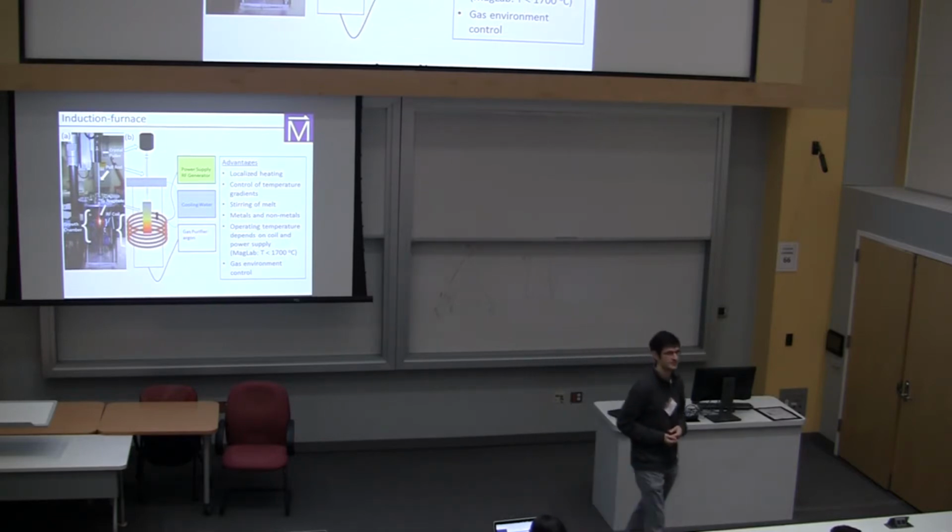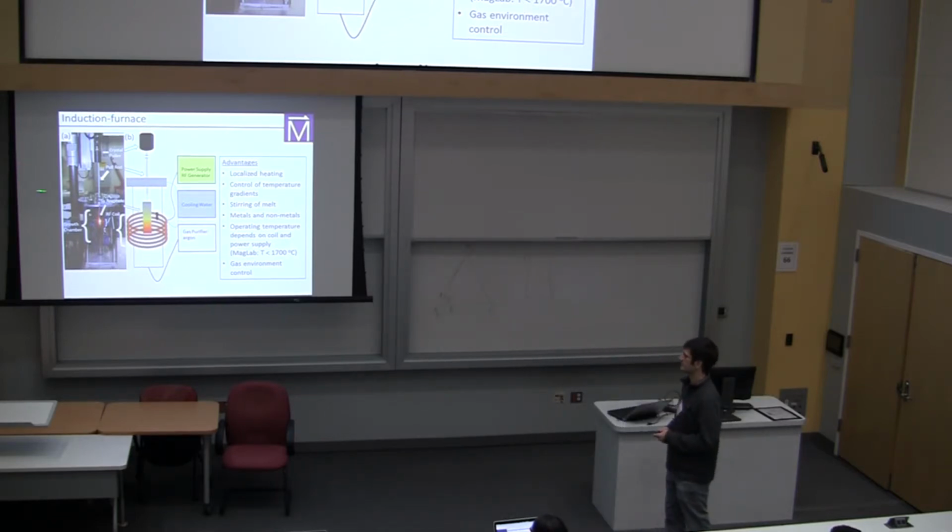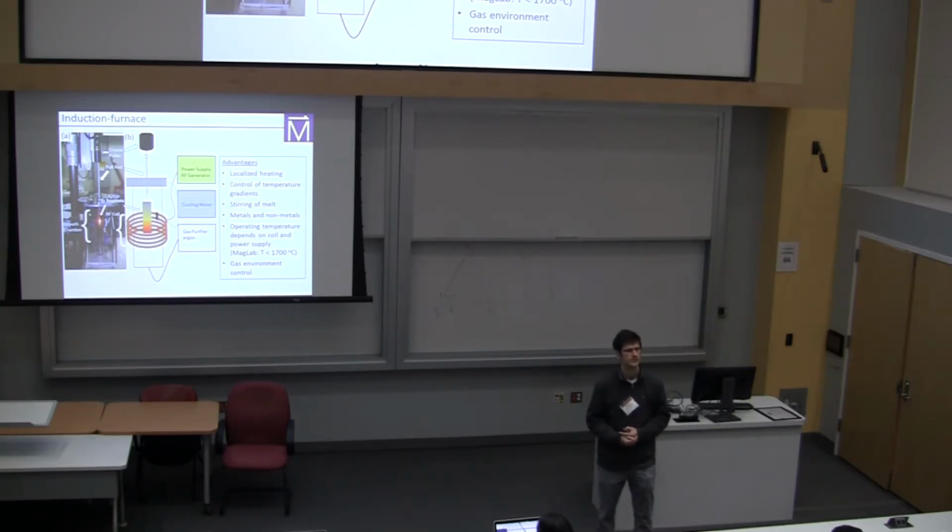That's difficult and costly. But if you run this at an overpressure of argon, if you have a little leak here, it doesn't matter, right? You can protect your metallic workpiece very well. And we can carry out these reactions on the order of 48 hours, 72 hours in this flowing argon environment and observe very little oxidization on the workpiece. But do you use industry-grade argon or grade 5.0?